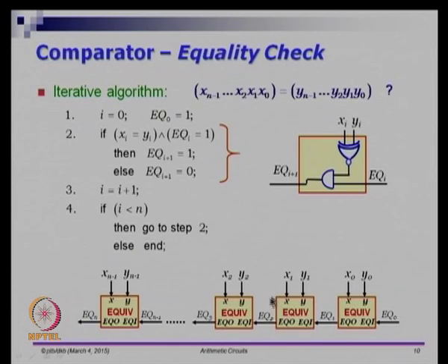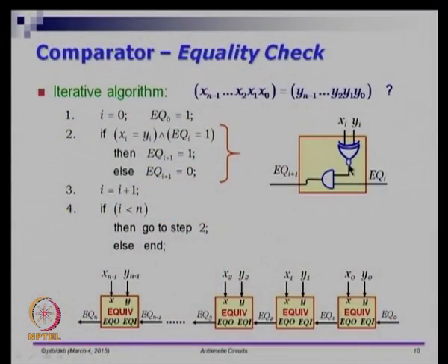So all we have done is we have taken the same bit slice and repeated it again and again, we just connected it. There are no logical blocks connecting them. That is the interesting thing about a bit slice circuit. In a bit slice circuit, all you are doing is connecting the wires together without requiring extra gates. So if I did this bit slice here, all I have to do is connect them together properly, and if I go and inspect eqn, it will tell me whether the numbers are equal or not. So this is a circuit which we can use for comparing unsigned numbers. So if there are unsigned numbers, I can compare using this.